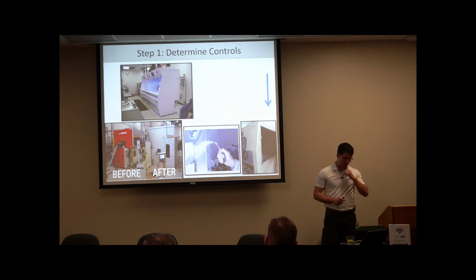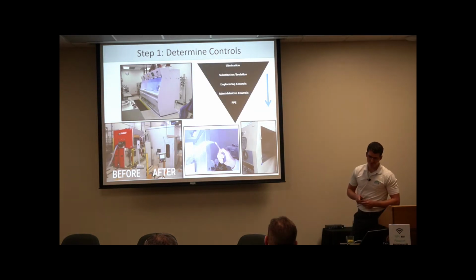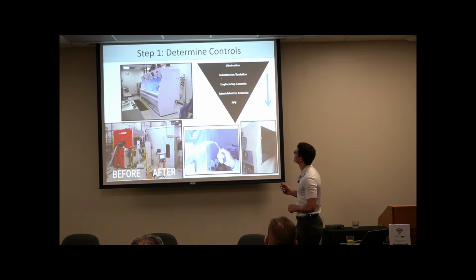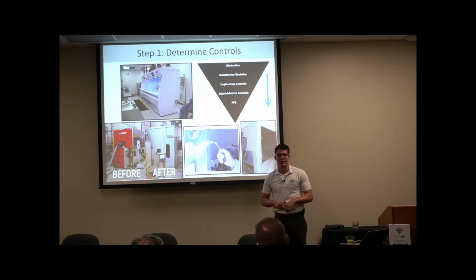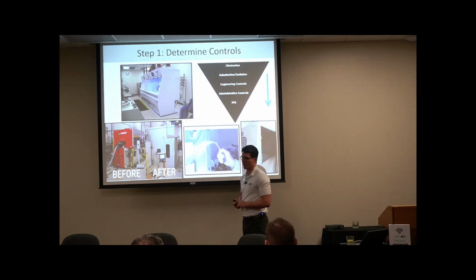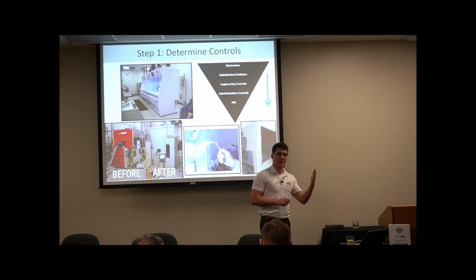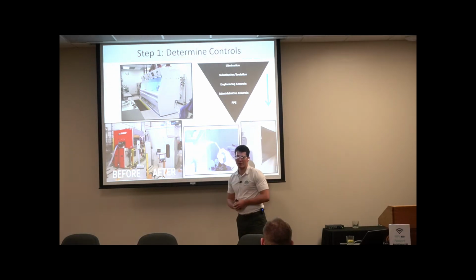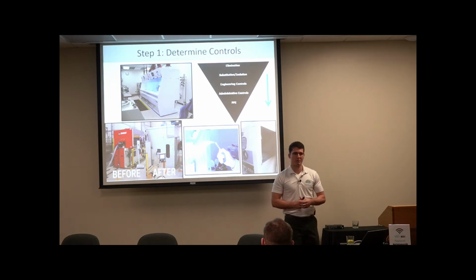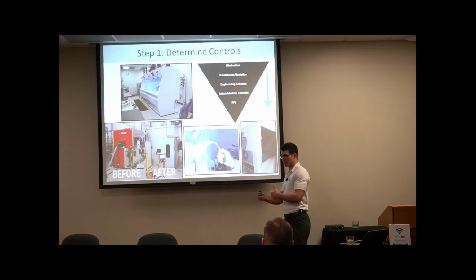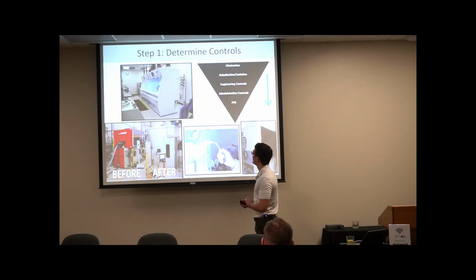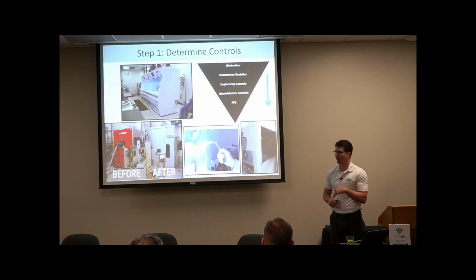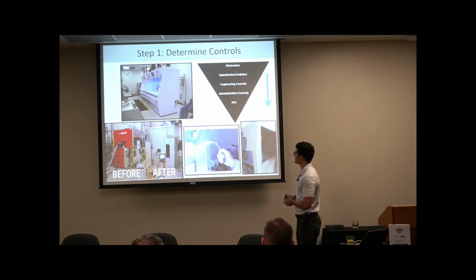Step one, very important, as I mentioned before. Of course, you have your hierarchy of controls. But what was actually not mentioned on Casey's hierarchy of controls was those first two steps right there, elimination or substitution. We recently had a case with toluene exposure where they wanted to use a certain coating that had a good amount of toluene in it, which has an exposure limit to it and is quite the respiratory hazard. But in that case, what we did was actually just substitute it out for a coating that could complete the same process or complete the same task, goal that is. And substitute it out for something that was less damaging, right? Or actually did not have any toluene in it. Excuse me. So that's definitely a route you can take.